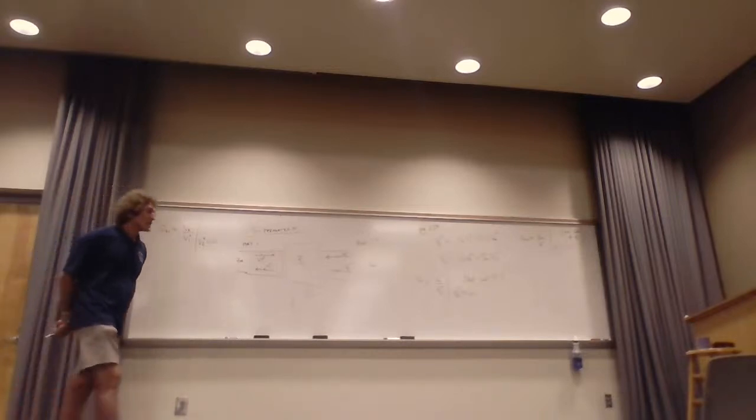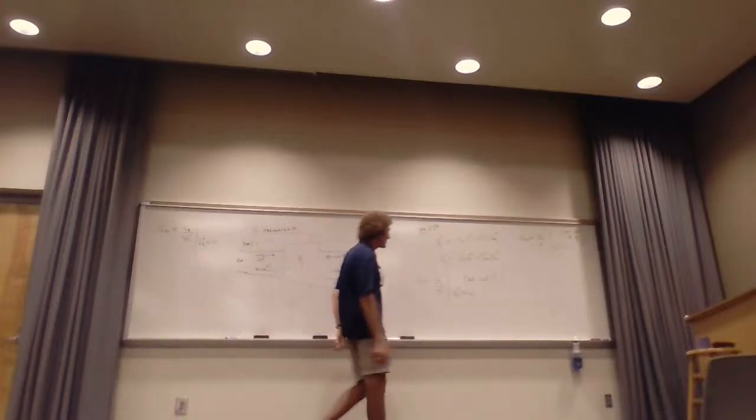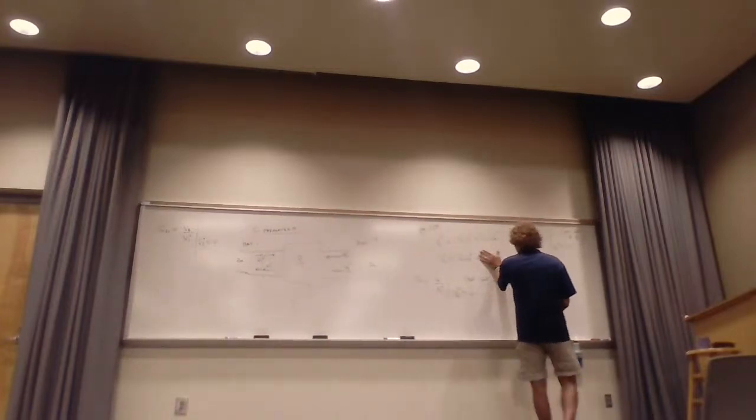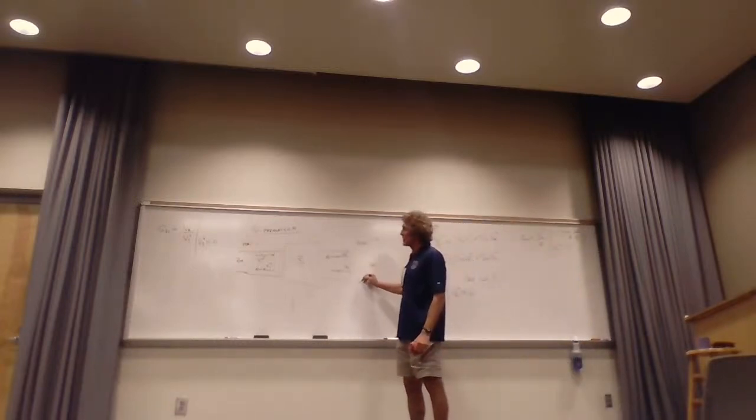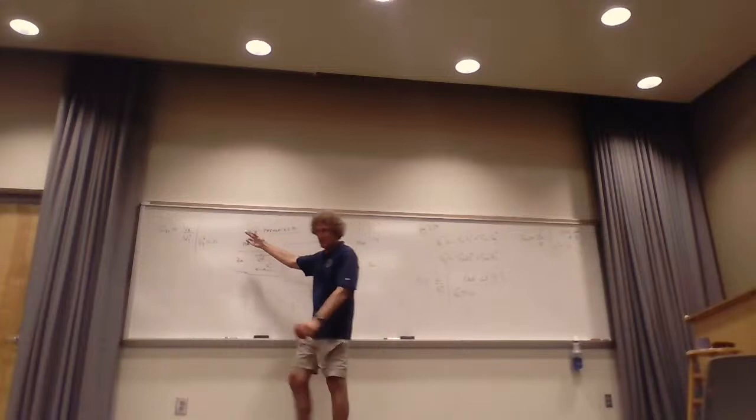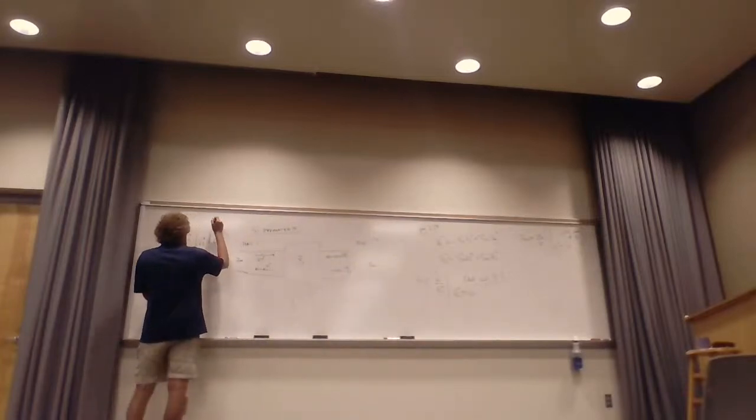Isn't that right? Now, what is that really? When V2 plus is 0, it's the ratio of output voltage to input voltage if this is into a matched load. That's the forward voltage gain. Write that down. This is the forward voltage gain.